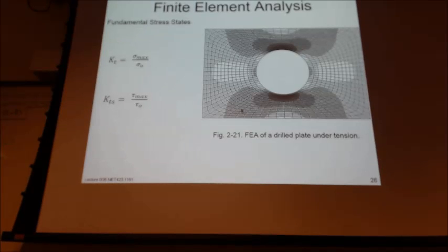We also have stress concentrations, and they constitute any discontinuity in the material, surface, or cross-sectional area. And these discontinuities create localized stress. And stress concentration values are developed through empirical testing, and charts are then created for reference. So a lot of those you just look up on charts or on the internet.